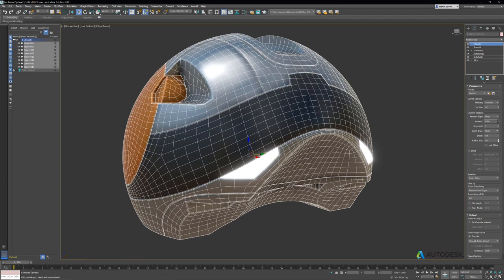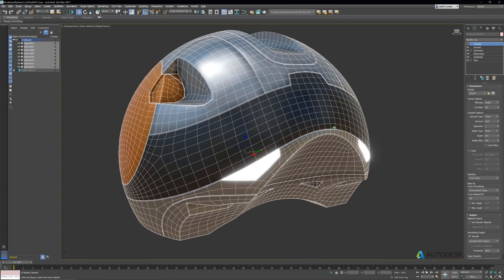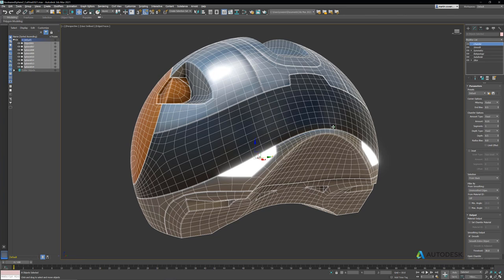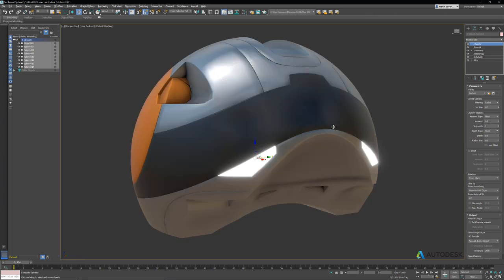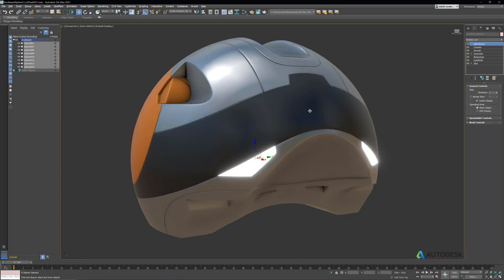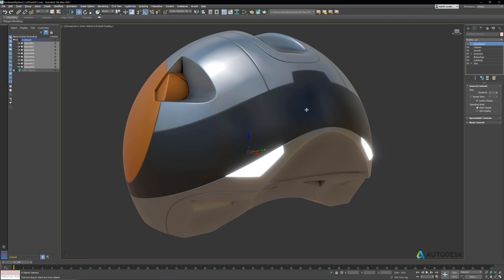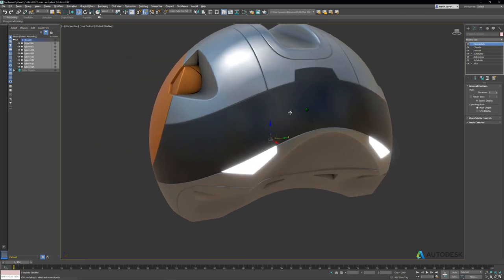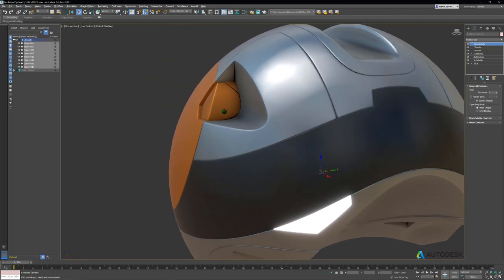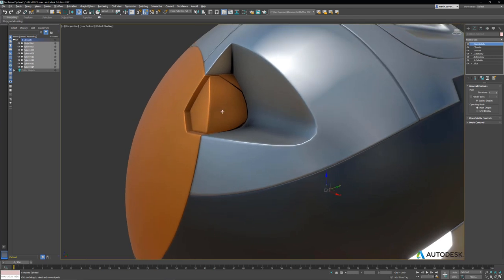Let's bring the amount down a little bit, and we can see we have a pretty clean mesh. We'll set it to mitering of radial just to be a little bit cleaner. Looks pretty good. Let's go ahead and add an OpenSubdiv modifier. Okay, I think that we're looking pretty good, but I see that there's a part right here that I'm not really happy with the way that bottom corner is shaded. So let's take a look at that.